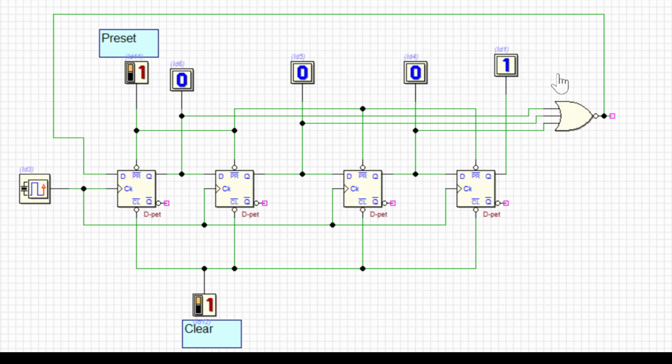So this is how we design circuits, counters or any sequential circuit so that it will not go to an invalid state forever. For every circuit you have to check for the lockout problem. If there is any lockout problem, you have to add an extra circuit so that it will not go into the lockout state. So this is all for today's lecture.